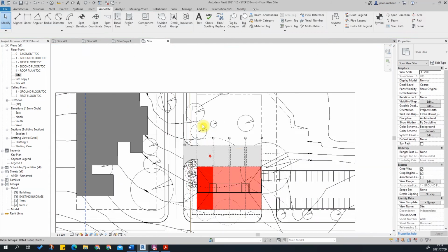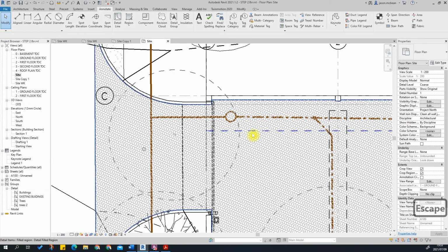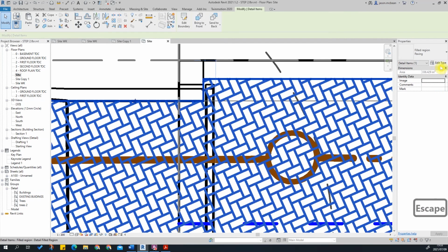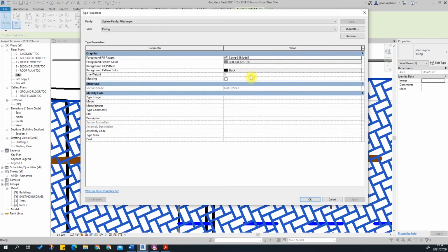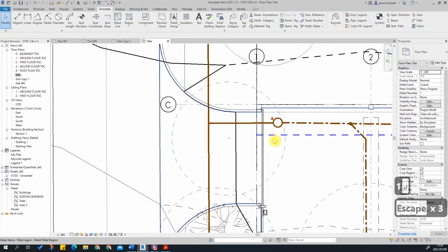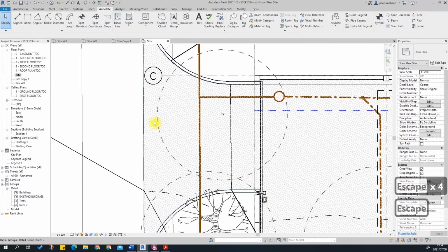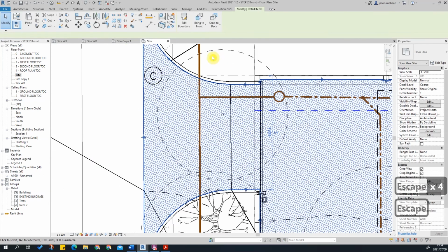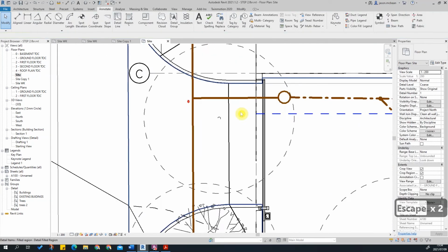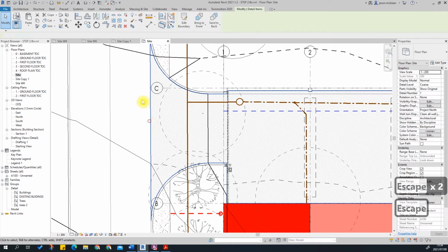Okay. Reset temporary hide. Now that's worked like a treat. The only issue that I'm seeing here is the line weight is incorrect in this hatch. That's a wake-up call saying, no, that should be 1. Just remember that, 1. Okay, that's working a lot better now. You can also send this, draw order, send to back, just like an AutoCAD send to back. So your other annotation objects are set above, just bear that in mind as well.